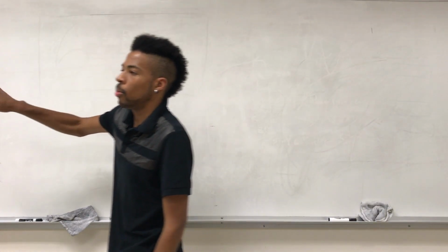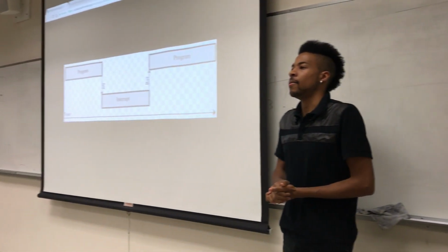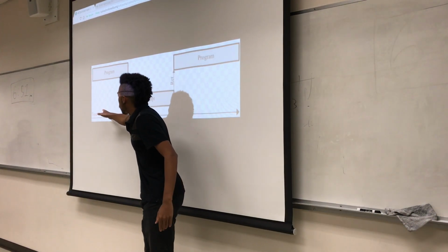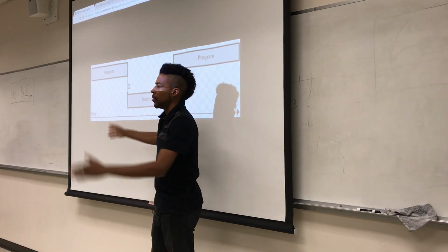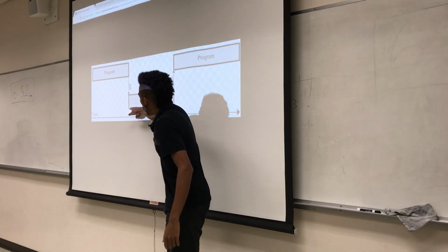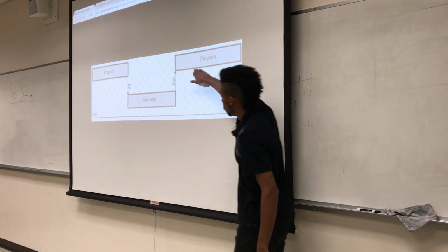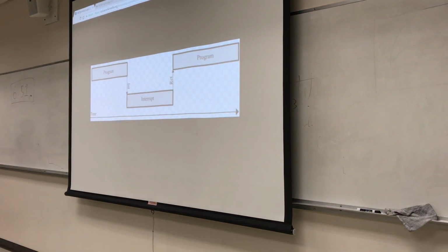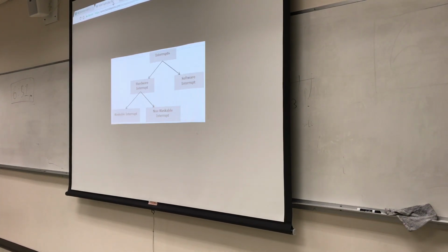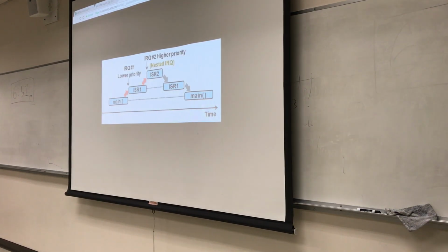The picture I have up here is just a normal, let's say, kind of run-of-the-mill interrupt. Your system has no priority system. It doesn't have any bias towards one interrupt or another. As it's running, you have your normal program processing through time. Then an interrupt occurs. It changes context, switches over to the service routine, and runs the interrupt. The interrupt then does an interrupt return, turns back to the program, and continues on its way, as you would normally see for most interrupts. And then we went over different types of interrupts: hardware, maskable, non-maskable.